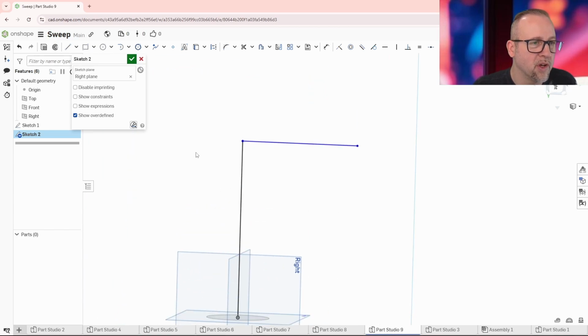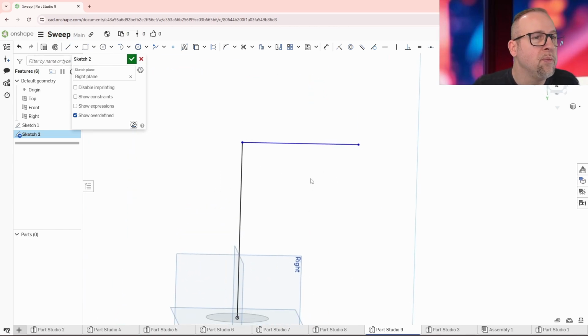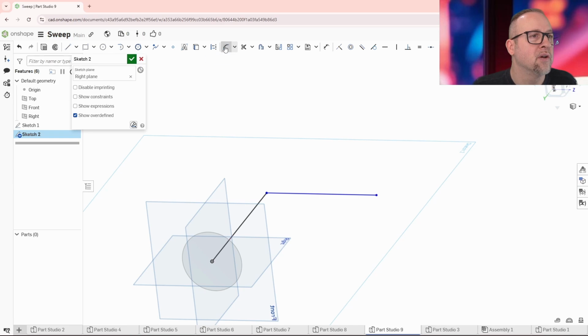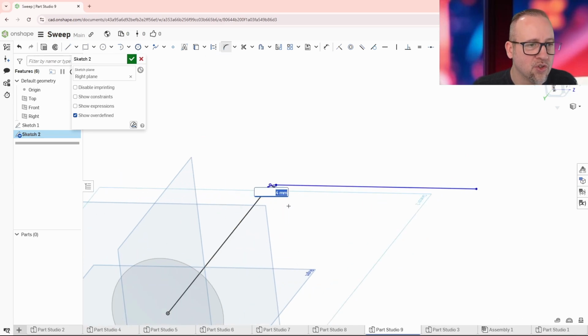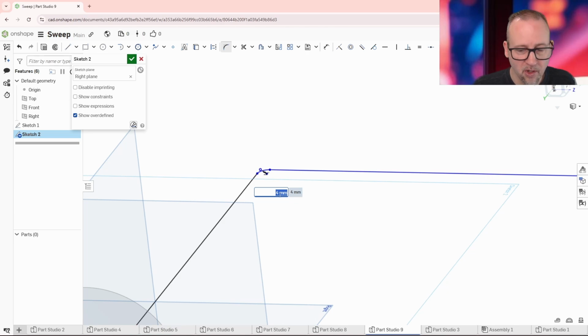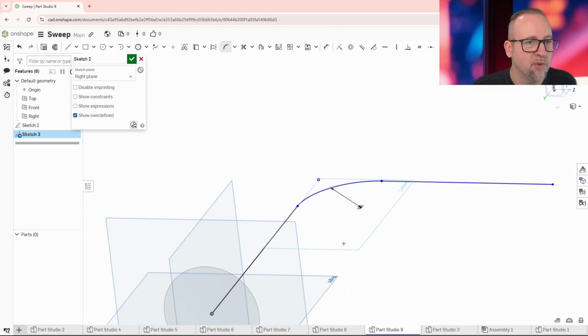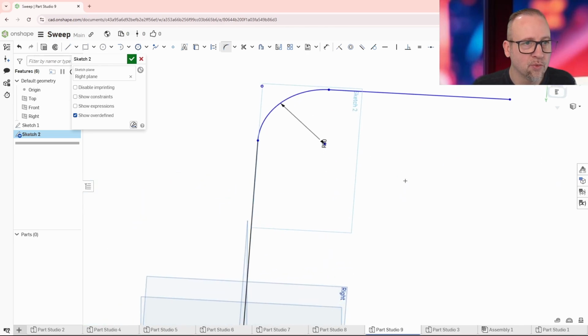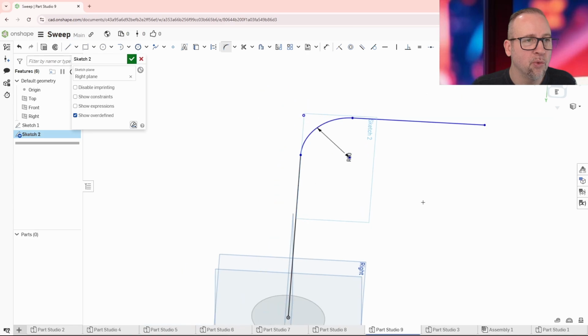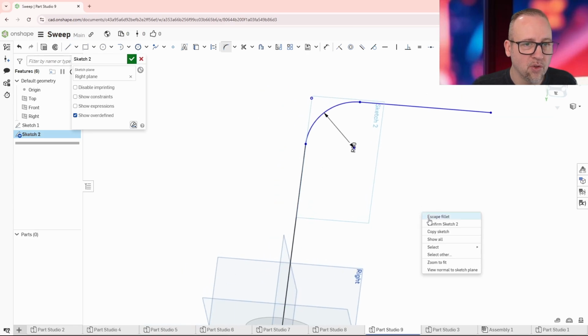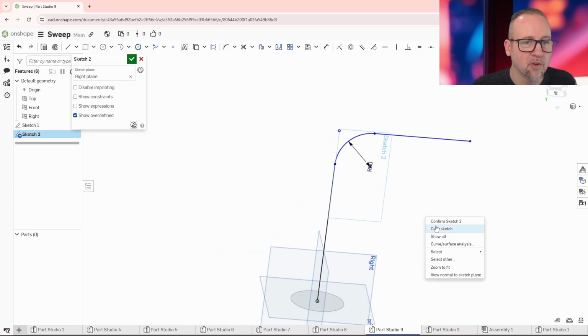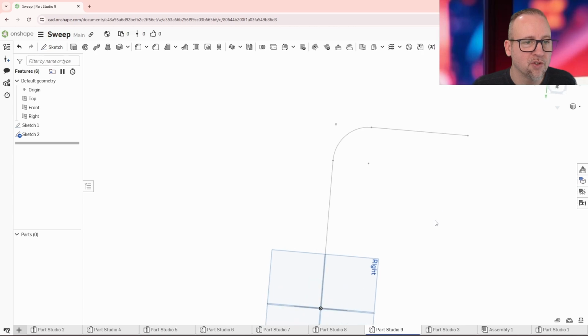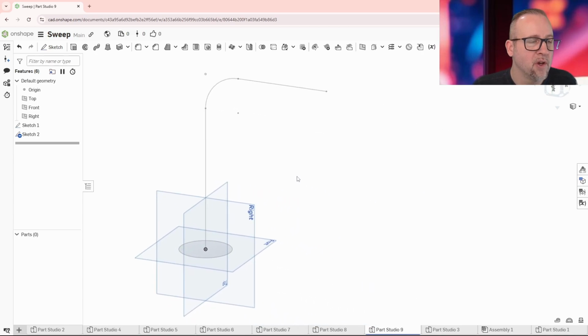And now we're going to put a nice sweeping radius here. Let's put a fillet, okay. It chose 4. I want to put like 50. Let's see what 50 looks like, okay. Looks pretty good. I believe that would be pretty good, okay. So escape that fillet and confirm sketch. Sketch is done, okay. So now we have our beginning circle and our sweeping guideline.